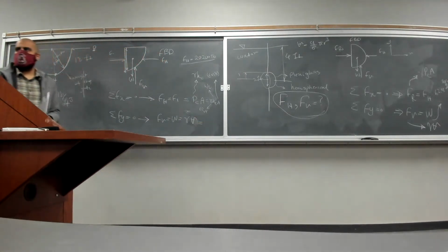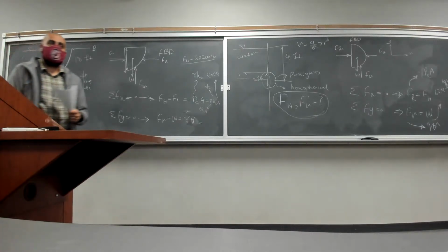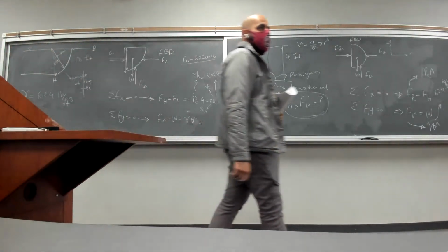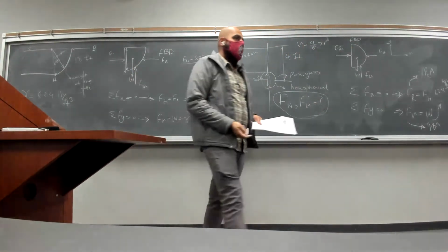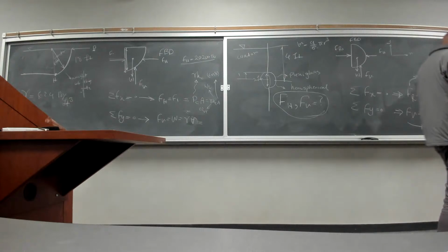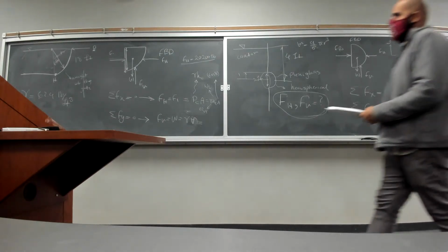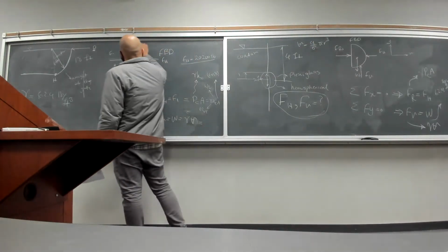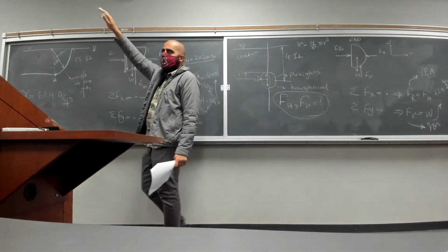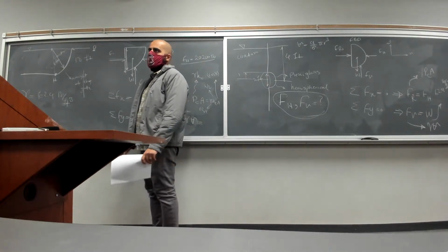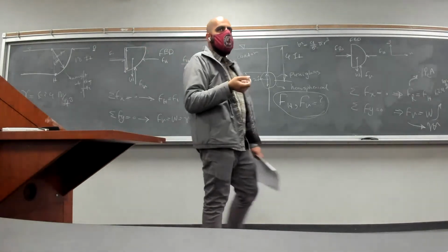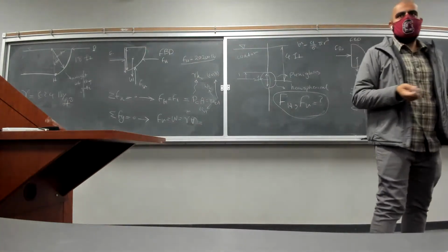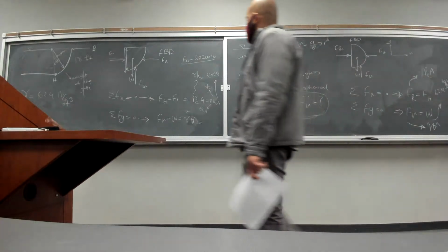We should do the same analysis for the vertical force in the other direction for weight. What is the volume of this body of water? How can we calculate this volume? It's going to be the surface area multiplied by the width of this gate, right? The surface area is pi r squared divided by 4, because it is 1/4 of a circle.